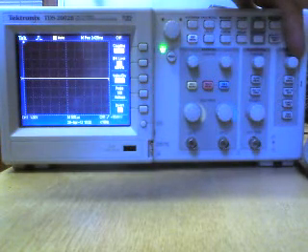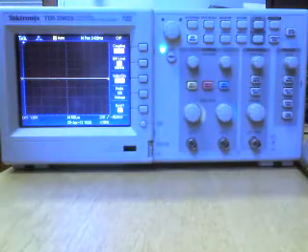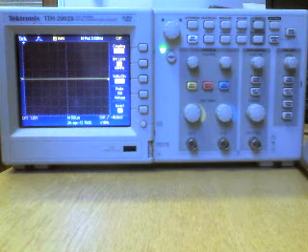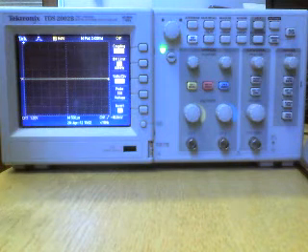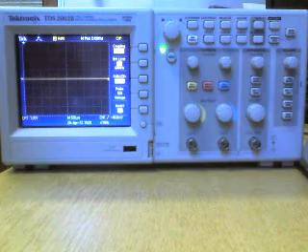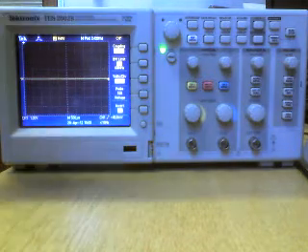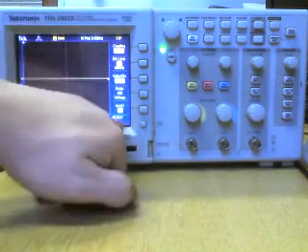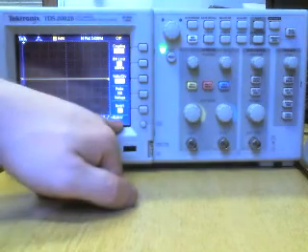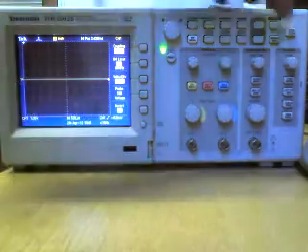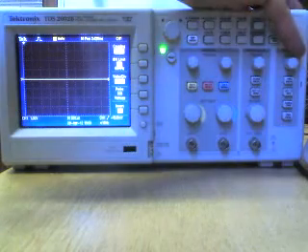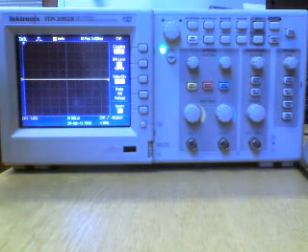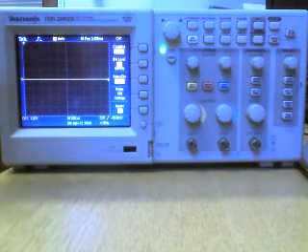So instead of having on the analog one had to guess where the trigger was, you had to move it very, very slowly until your waveform was stable, and then slowly tweak it till it got to the beginning of the wave, where it's in the centre of our sine wave, point of no change. In this case you can actually see where the trigger level is. It's got a nice arrow next to it, and not only that, it gives you the actual voltage of the trigger, which is quite nice. Makes life a hell of a lot easier. So you can just flick the knob and there you go, presto, it will be in the sine wave because you can actually see it within the voltage of a sine wave.